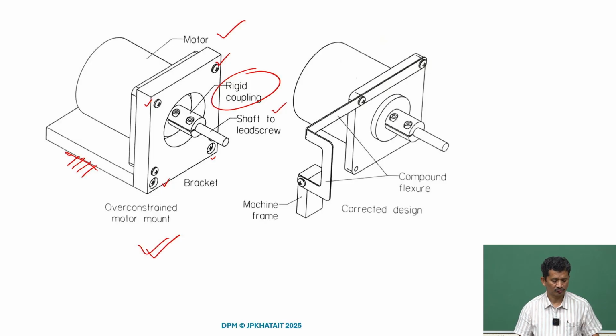And so, any deviation, any misalignment, any offset, when it starts rotating, although the idea of the motor is to just rotate the shaft without giving any other forces, since it is rigidly connected, because of the offset and misalignment, there will be huge forces generated, and the company encountered a lot of problems with these units.